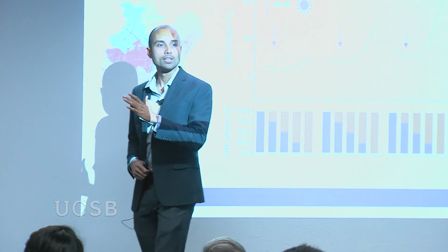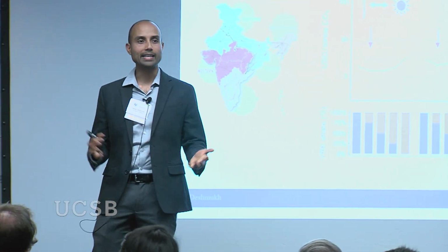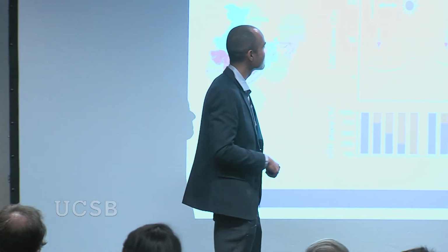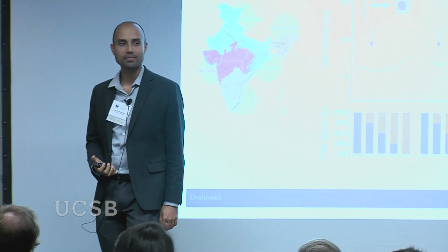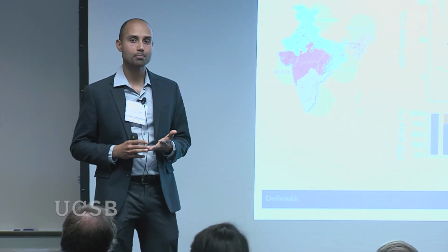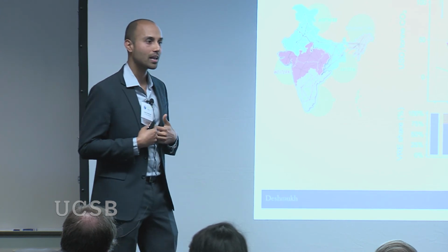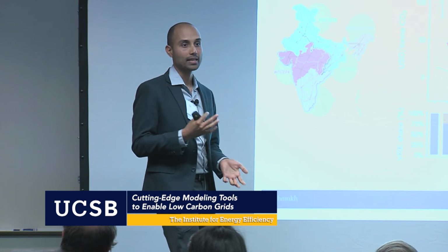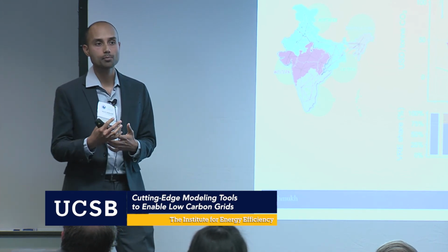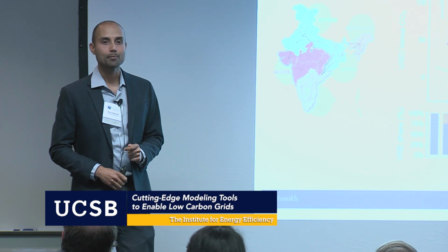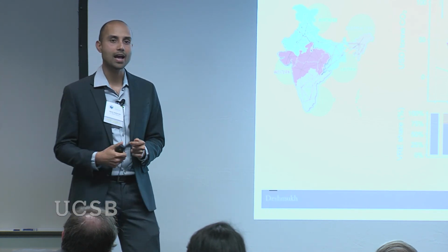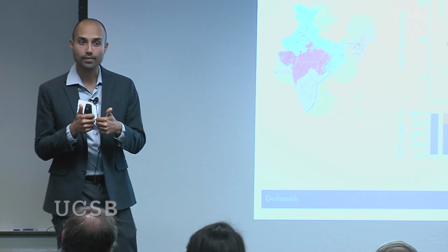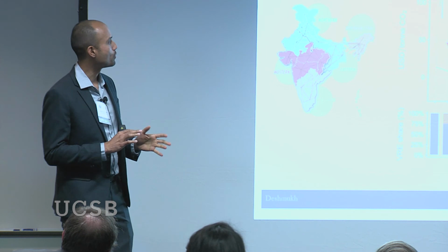It's that duck curve. That duck curve, which looks like a camel in India for whatever reason, the way it's shaped. But we curtail a lot, at least based on this model. That's because the coal-fired power plants are not very flexible. Here in California, we use gas plants, which you can turn down much more, and you can shut down and then start up again. Coal plants, you can't do that because these are all steam-based turbines. If you shut it down, you have to keep it down for like 24 hours, so it's very inflexible. So that's a pretty big reason to be wary about solar.